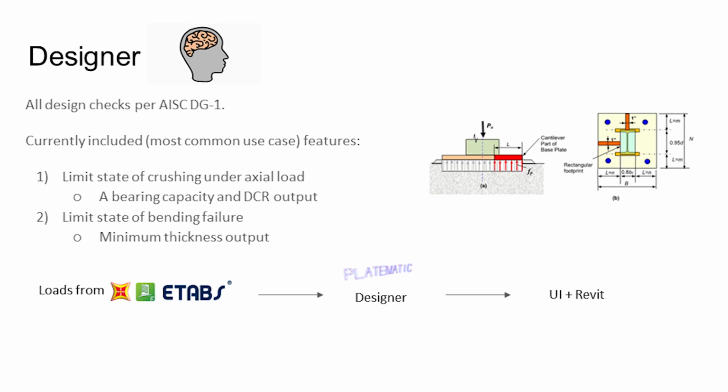And then once you have the base reactions and the forces and all that good stuff, we can use some sort of designer that Shri worked on and use the simple AISC design guide equations to spit out: does this base plate design work? What's the minimum thickness? What's the maximum bearing capacity? And then send the results back to the user interface.